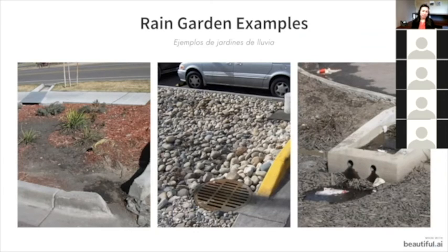We have looked at this really bad example of a rain garden several times already on the far left. You can see the number of issues that are happening here. The landscape was installed too high. You can see the darker spot on this picture where the water is pooling and sitting. It doesn't even move all the way through the rain garden. It looks like it's just being stopped because of all of the pollutants in there.